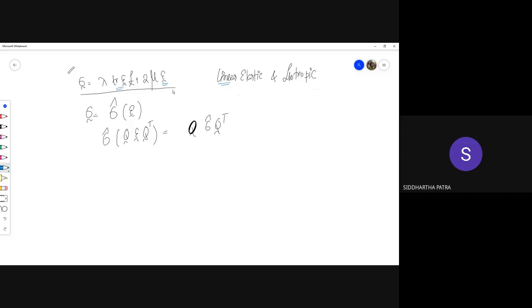The reason I know this is elastic is that for a given value of strain, and this time by value I mean the entire 9 components of the strain, values of each of the components, there is only one stress value. Because again, this representation is linear, it doesn't matter whether you are loading or unloading, whether you had previously loaded to a certain stress value.